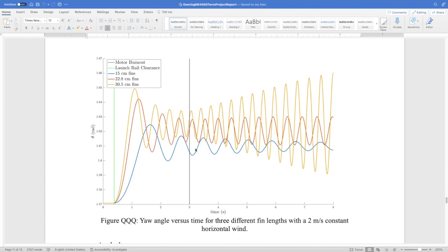because if you put the center of pressure forward, or above the center of mass, in the rocket, then the rocket will just flip over. It's impossible for it to be stable at that point. So this thing is marginally stable as it is. Making it that way results in damped oscillations, and also just lower weathercocking.